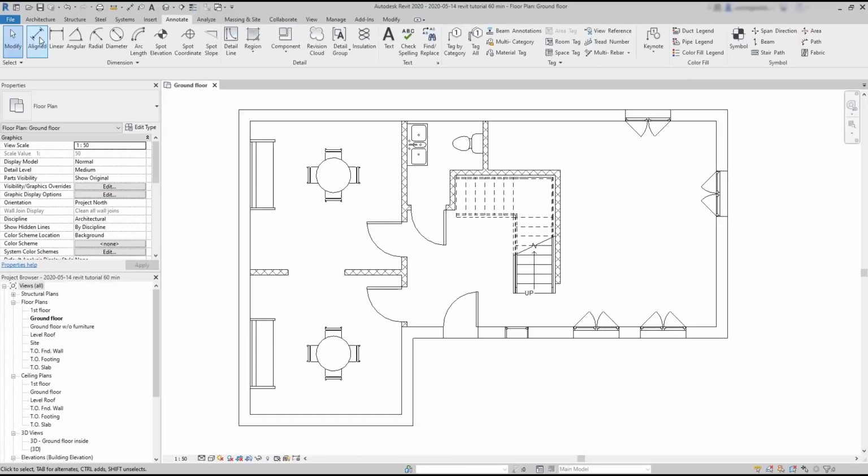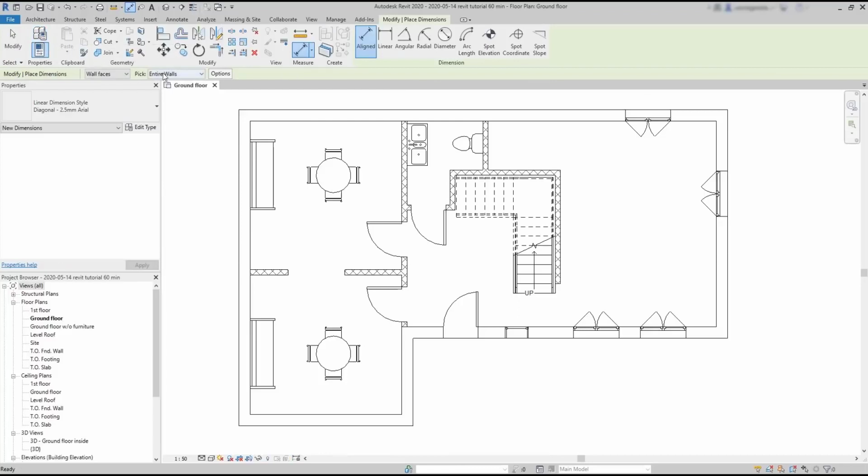In the next example, I'm going to create a dimension line, but this time using individual references. I pick these two reference lines. Then, to place just this dimension, I just click anywhere away from an individual reference. That's what I showed you before. But let's repeat this.